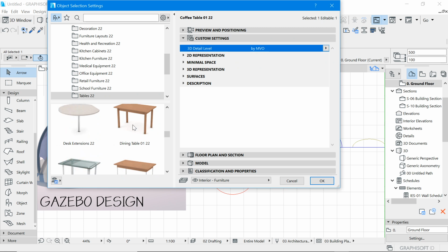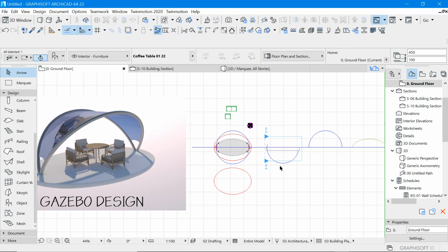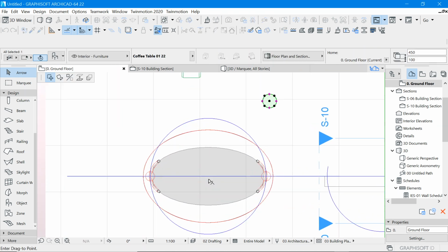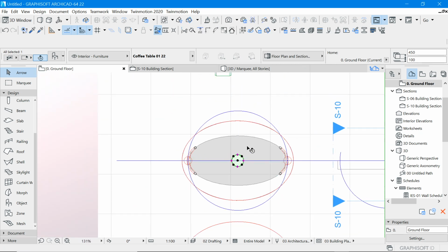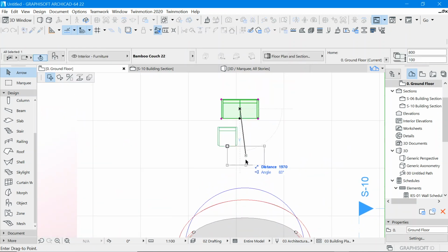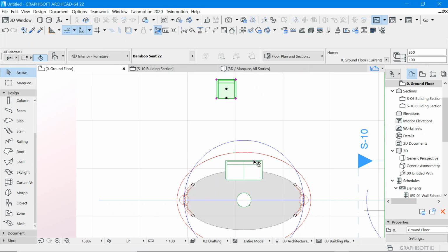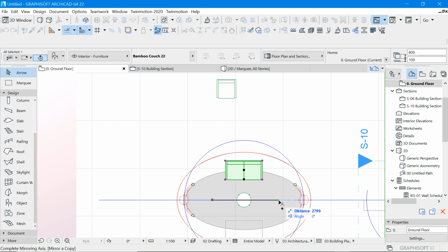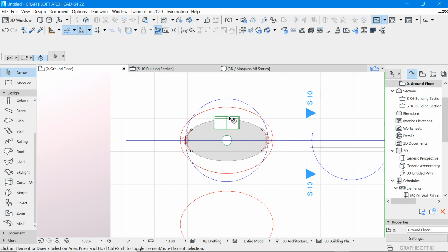So let's pick, I don't know, let's go with the square table we have. Okay, this one will work also. We bring it in the center. If we can't see the center, use the circle, pick it, then pick this chair, bring it. We can have it along here. Then maybe we can straight away mirror a couple of that along our axis. If these chairs look slightly far away, could bring it slightly inside, then mirror it again,